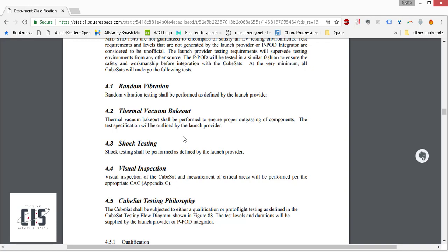I'm not sure if they'll actually be measuring if we lose mass. I think they'll be measuring condensation. So this is not a test of whether your thing survives hot and cold? Well, slightly that, but it's mostly to see, part of it is you can get rid of some of the stuff that would outgas by doing a bakeout. After that point, I'm pretty sure they're going to do this testing for us. Then they'll just keep it in a sealed container so nothing recondenses on it. So when it goes up into space, it doesn't have as much outgassing, even if that already would have been less than the limit. They're just trying to further limit it a little bit.